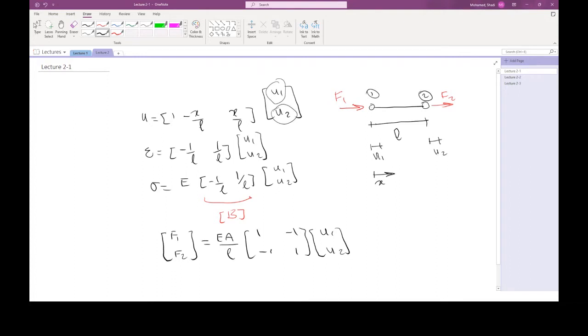The displacements we are free to work with and change are the nodal displacements, and the forces are applied at the nodes. So can you consider a force that is applied here? For example, F3 here. This is something you cannot do because all the loads and the displacement are associated only to the nodes, nothing else. Otherwise, the element is not going to work. This is quite an important assumption to remember. And pretty much everything we are going to discuss today is more or less related to this assumption here.